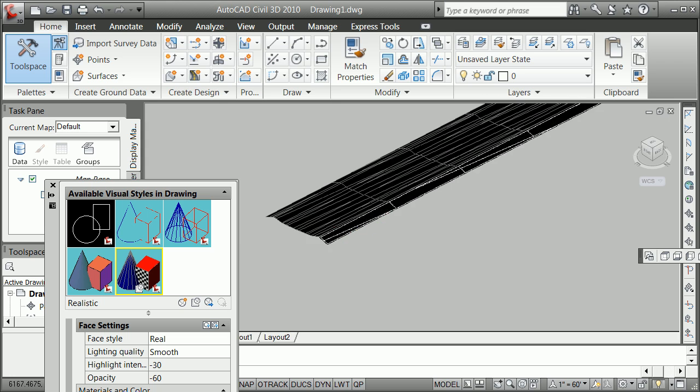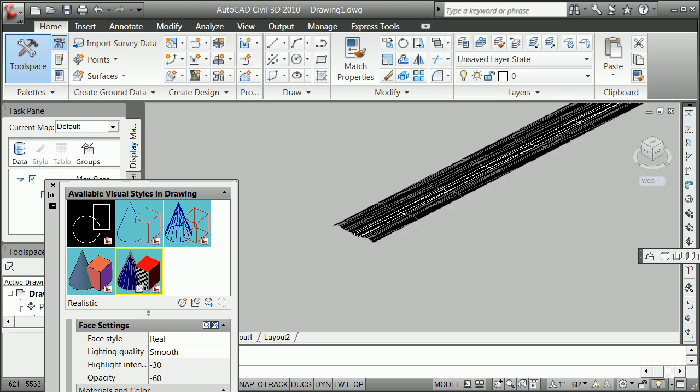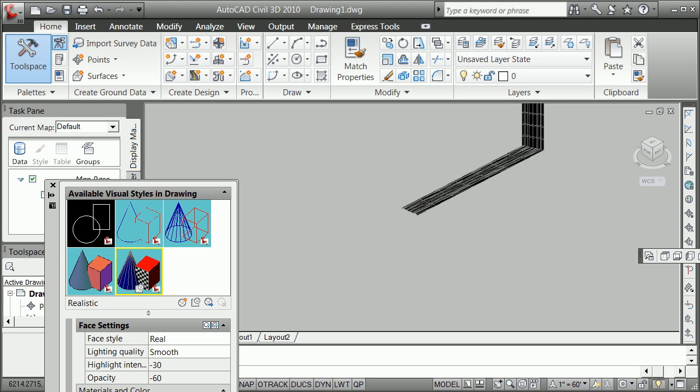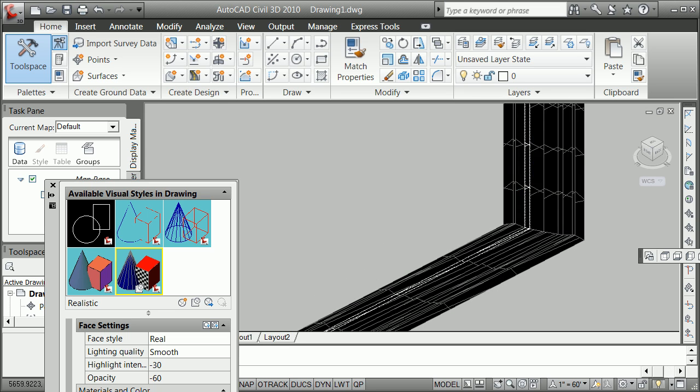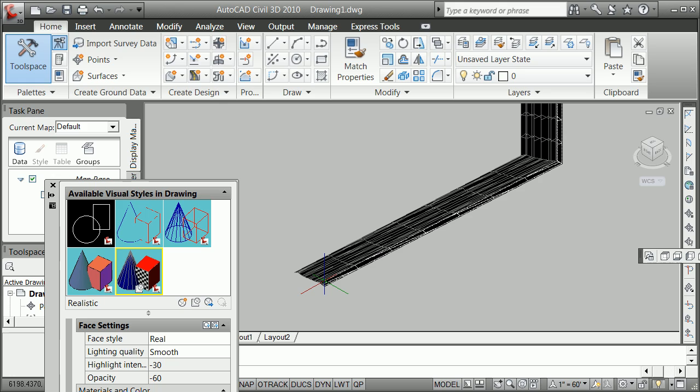So you start to see that this pretty much, who knows what it did around the turns, but this is pretty much what we asked it to do. It's not perfect, I'll point out, but it's pretty close to perfect. It's got a little overlap here, it looks like, when it did this, put it through, and so we'll have to play around. This essentially is a tool that one can use to do a quick one-off if you have a 3D poly. Remember, lines can have 3D elevation. Endpoints can have different elevations. Polylines cannot, but 3D polys can.